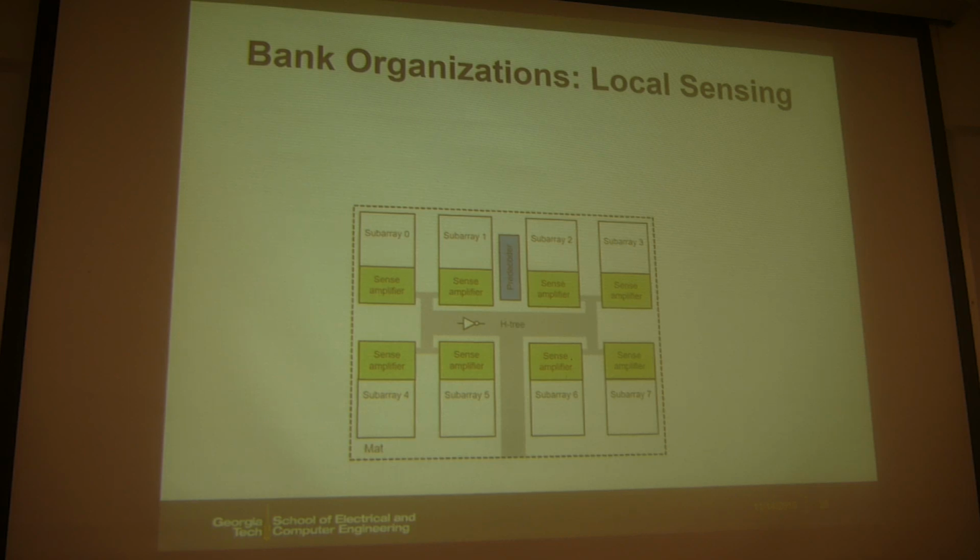And also for the routing, from the higher level point of view, you just think about how you get the data from each subarray. Typically there's a routing called H tree. Every intersection here is 2 branches. You go left or go right, and then here you go up or down, and then again left and right.